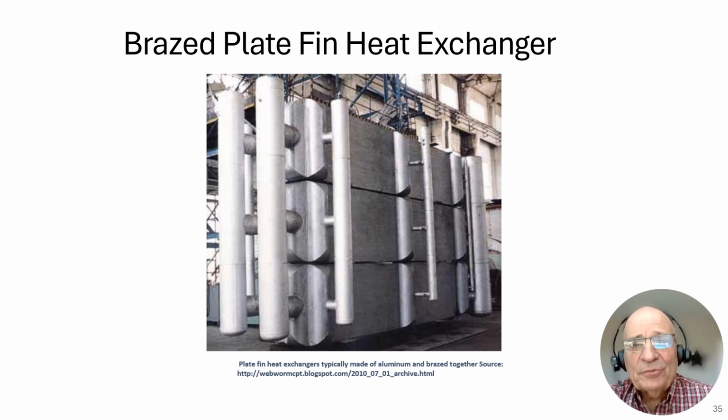This is what a finished product of a brazed aluminum heat exchanger looks like. As you can see, it's a marvel of engineering and workmanship skill. However, I give you one caution, and that is that aluminum and mercury are not friendly to each other. Mercury aggressively attacks aluminum. If we started this discussion today, and I started with a drop of mercury on an aluminum plate, by this time it would be halfway eaten through that plate.